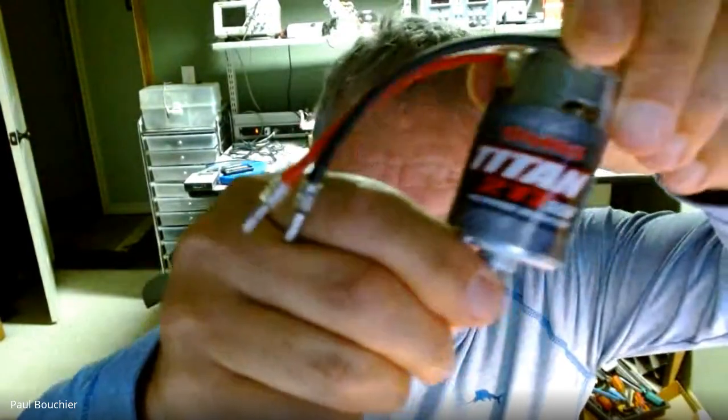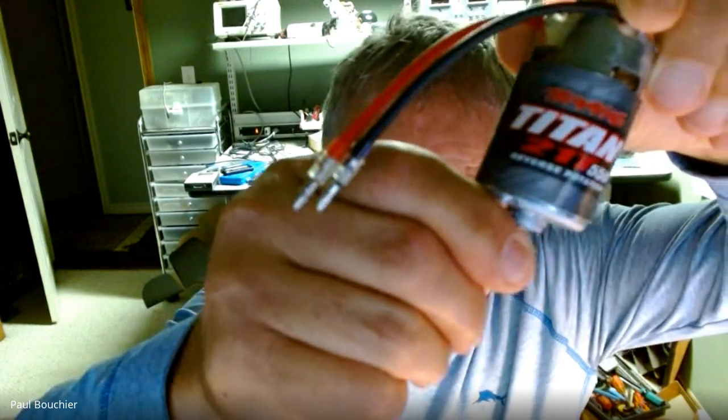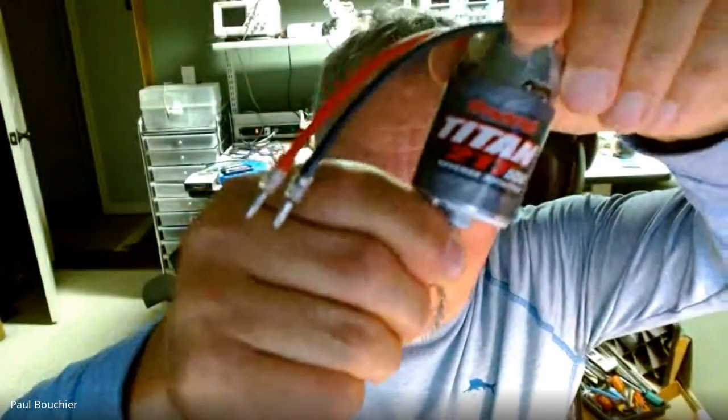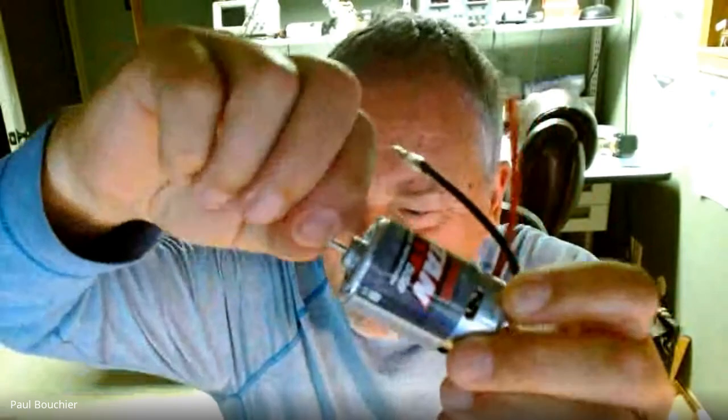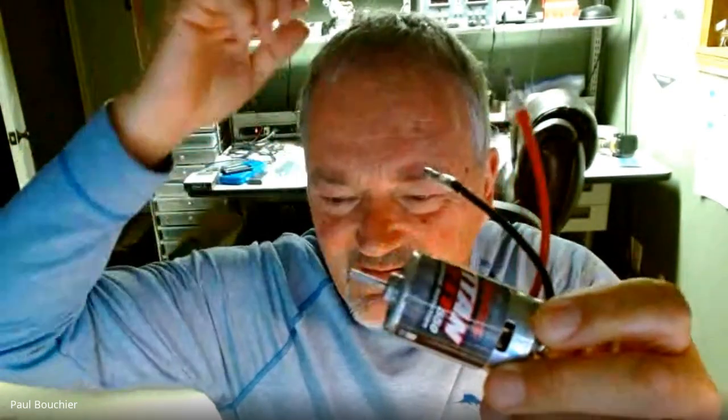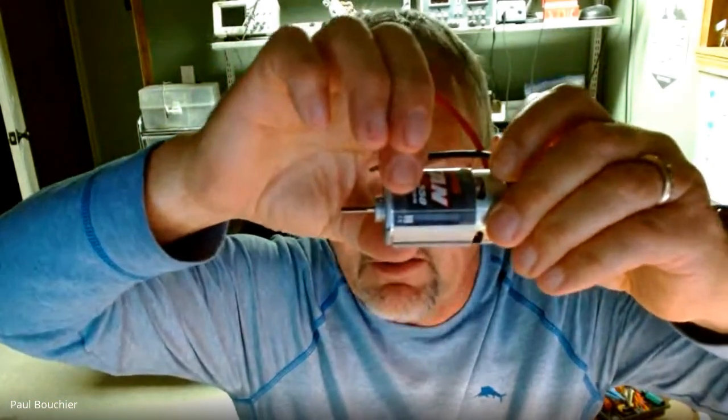I go to my pack rat zone where I've accumulated motors from Tanner's. Yeah, but not modern stuff. You wouldn't find this at Tanner's, I think. This is more modern brushless RC stuff. Oh, RC, yeah, no. And specifically what I'm trying to replace is this Titan 550, a brushed motor that came with the new robot kit. It's got a flat on one side of the shaft, so I need to find a motor this size that fits in all the mounting but is brushless DC. Okay. Yeah, probably RC hobby car type places. They'll sell that.